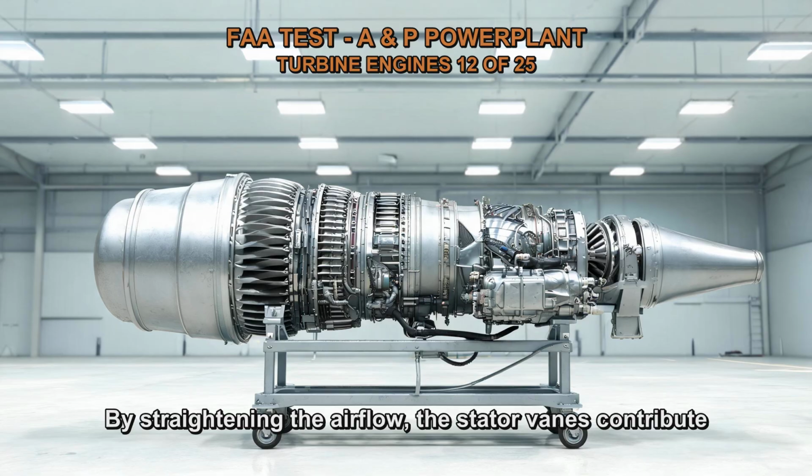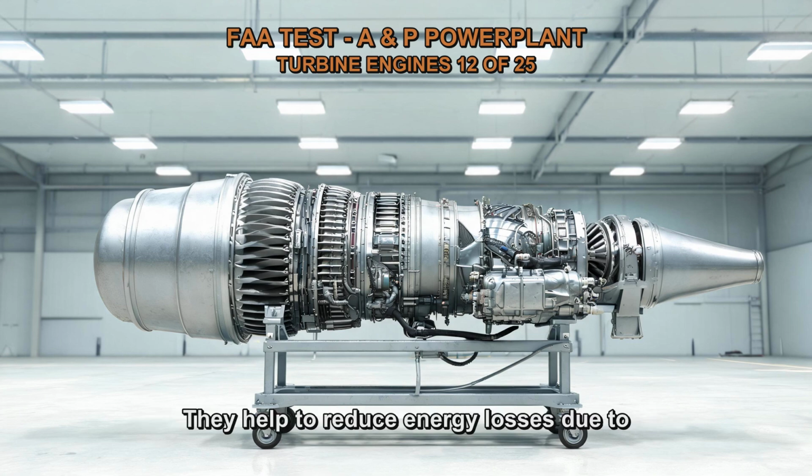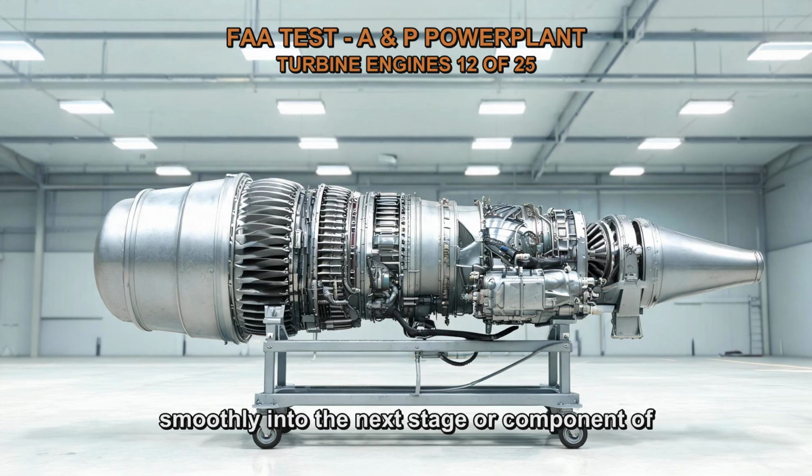By straightening the airflow, the stator vanes contribute to improving the efficiency and performance of the compressor. They help to reduce energy losses due to turbulence and ensure that the compressed air flows smoothly into the next stage or component of the engine.